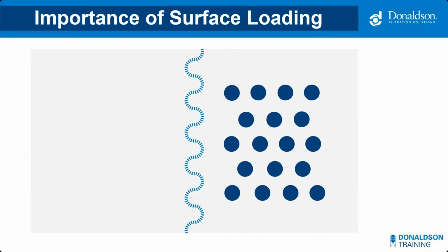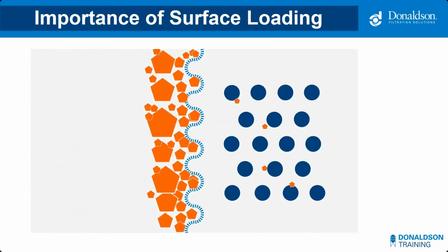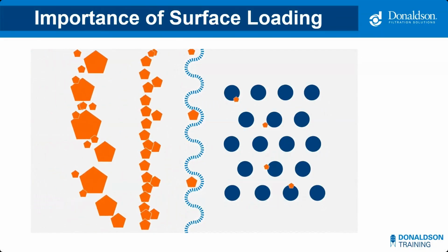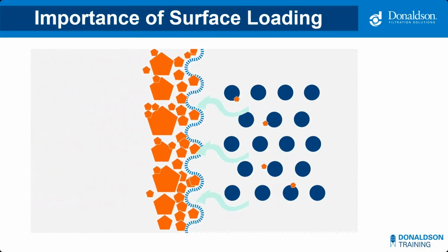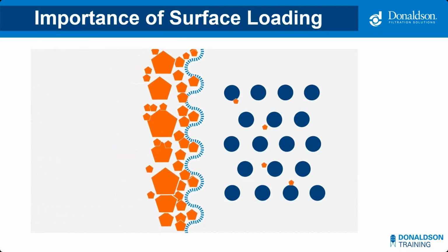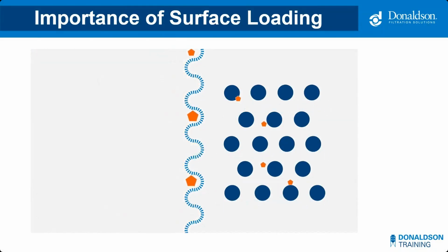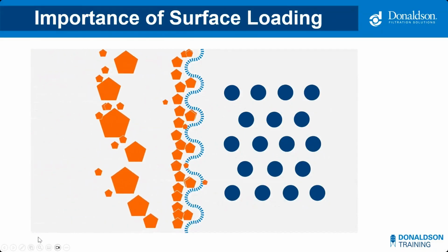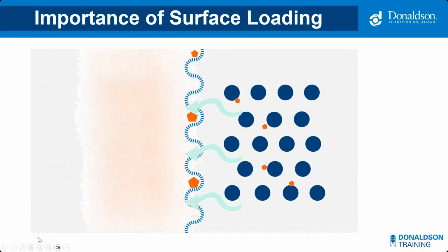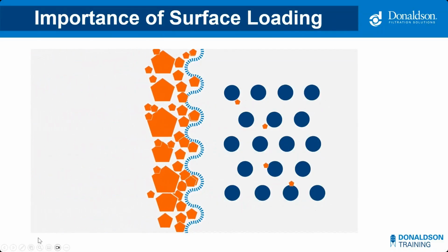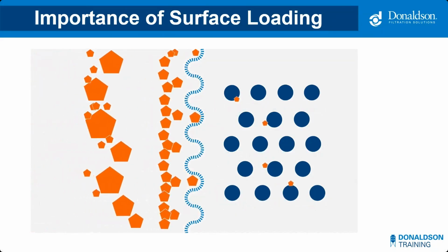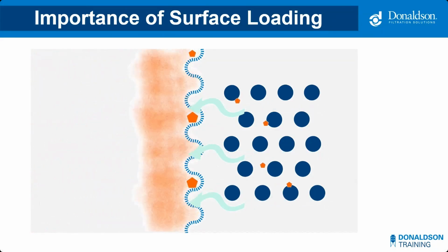So this is a fun little simulation. We can get it to play here. There we go. Kind of shows what I mean. You can see that around here we like to say dust filters dust, right? You do want some of that dust on the surface of the filter because the varying particles help improve efficiency. You can see that some of the finer particles get through, but the larger particles, once they're on the filter, prevent that. And as we pulse off, the dust cake gets rearranged and dust falls into the hopper.